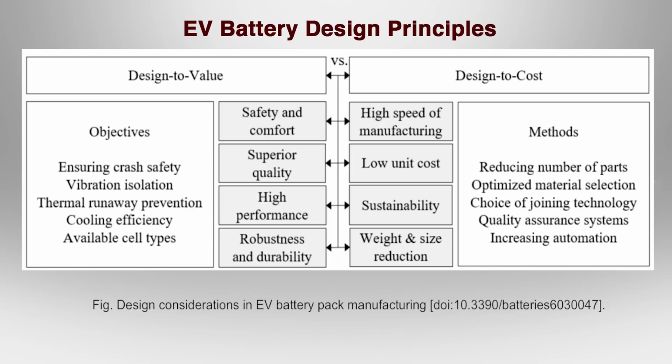There are various methods. In some cases where vibration is more, we use flexible connectors in battery packs to connect two different cells. However, the cost is very high because flexible connectors are very costly. So depending upon your application, you have to select some other component instead of using the standard one. It totally depends upon your performance and your cost. So in general, there is a trade-off between performance and cost.